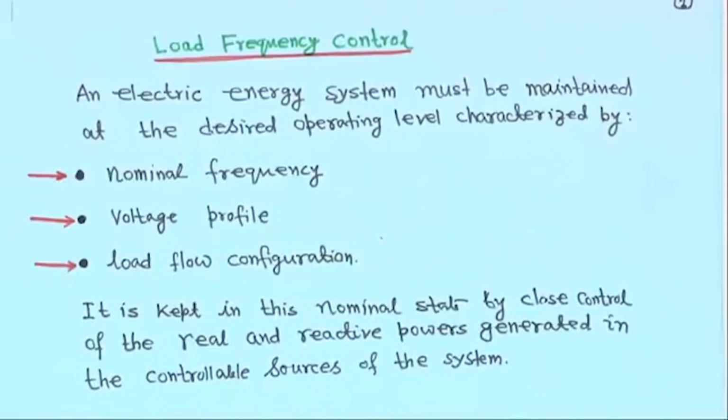In load flow studies, as we have seen in the power system analysis course, there is the decoupled load flow. In the decoupled load flow, if real power changes, then the voltage angle changes and it leaves the bus voltage magnitude almost unaffected, and if the voltage angle changes, the frequency is changing, either f or omega, the way you take it.